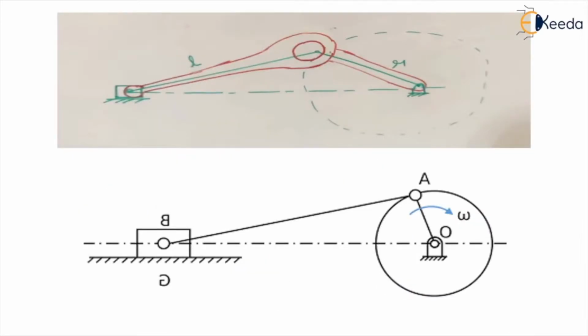Now we have already discussed the complexities of the connecting rod in a slider crank mechanism. We have already talked about why the consideration of the inertia force of the connecting rod is quite difficult, because of the non-uniformly distributed mass and the complexity in the motion of the connecting rod, because a part of it is connected to a rotating body and a part of it is connected to a reciprocating body.